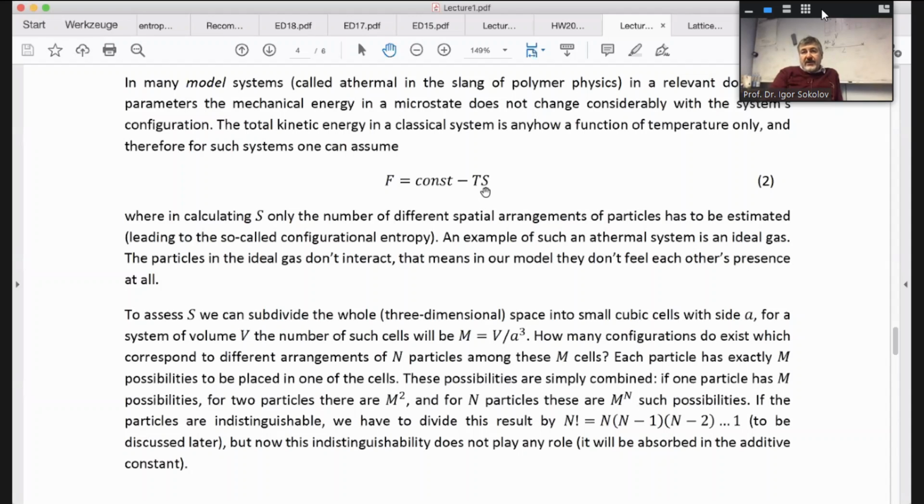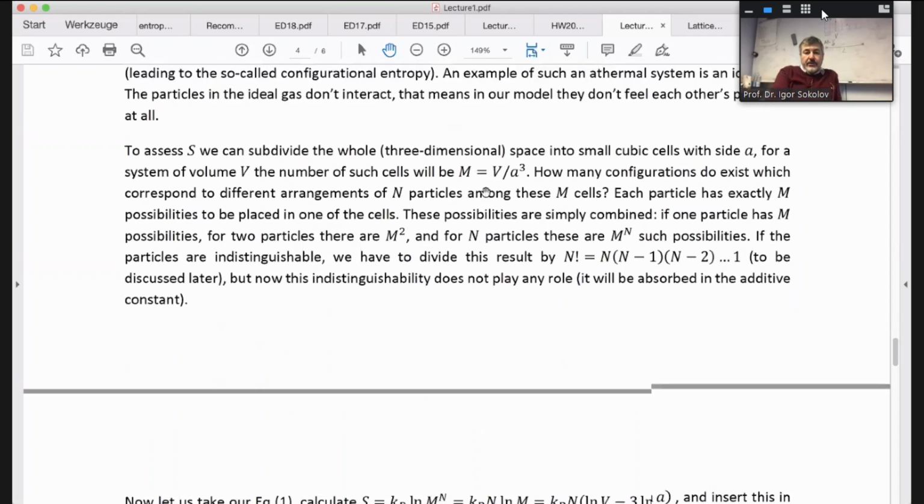Most forces in polymer physics, like the rubber elasticity, tension force of polymer molecules, and so on, are at least at small elongations of entropic nature. If you pull too hard, or if you extend too far a polymer system, then you will see forces due to change of the internal energy. They are already connected with strong deformation of chemical bonding, with change in chemical bonds. But at small elongations, practically all forces, if you look at single polymeric molecules or simple polymeric materials like rubber, are of entropic nature or can be approximated as forces of entropic nature.